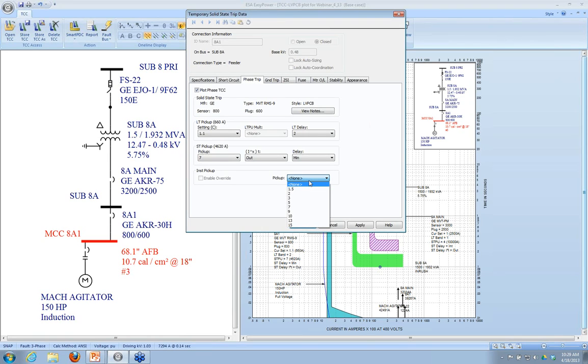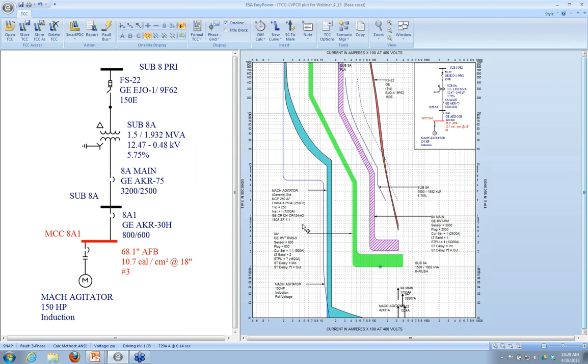And that's true of most of the older trip units that are out there. So most of the newer breakers probably have a switchable instantaneous, whereas you can turn them on or off in the field. But for older breakers, older trip units, I would not count on that. You need to verify. If you want to get rid of the instantaneous or put instantaneous in, it may involve replacing the trip unit.